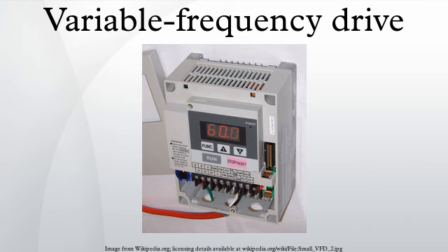Operator interface. The operator interface provides a means for an operator to start and stop the motor and adjust the operating speed. Additional operator control functions might include reversing, and switching between manual speed adjustment and automatic control from an external process control signal. The operator interface often includes an alphanumeric display and/or indication lights and meters to provide information about the operation of the drive.